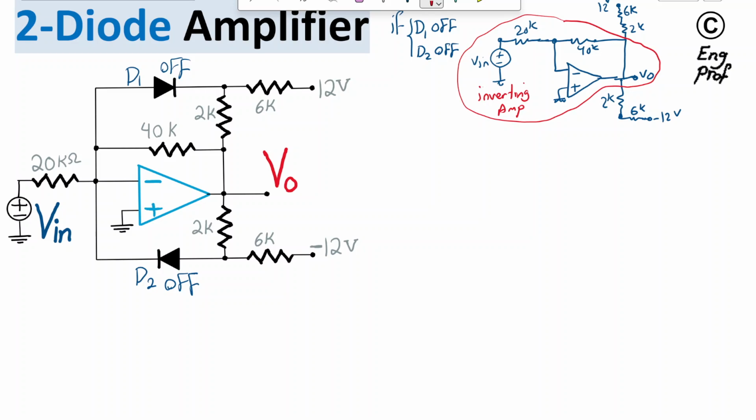And as is known in this case, the gain of this amplifier comes from writing the KCL, or Kirchhoff's current law, which says this current should be equal to this current, obviously. And because of virtual short, we have 0 volt here. Virtual short enforces that the op-amp has the same voltage at the negative and positive input terminals. So as a result, 0 volt appears here as virtual ground.